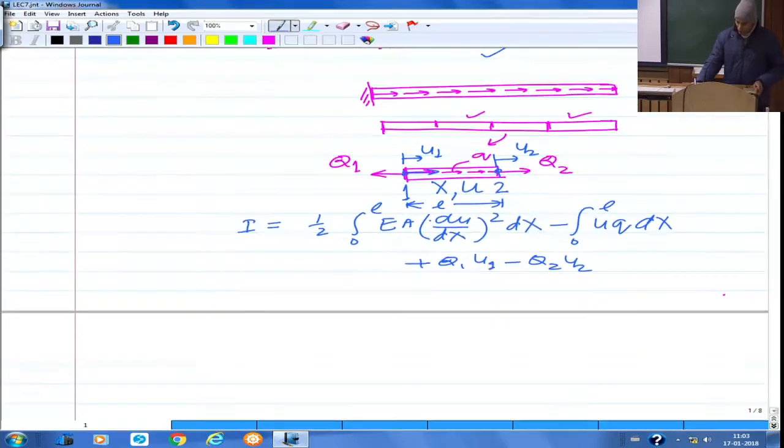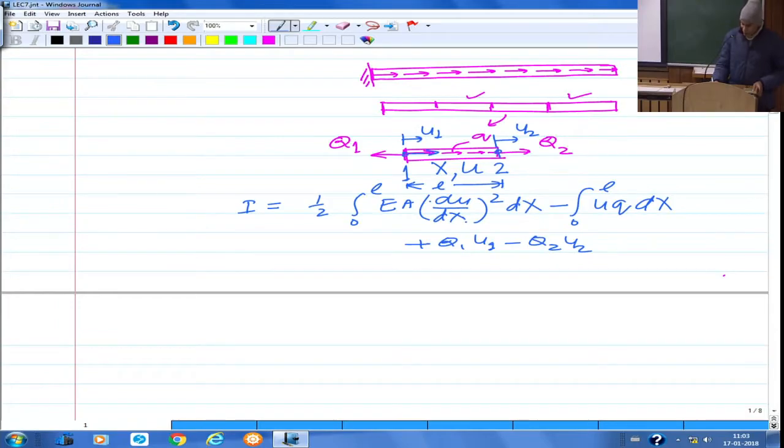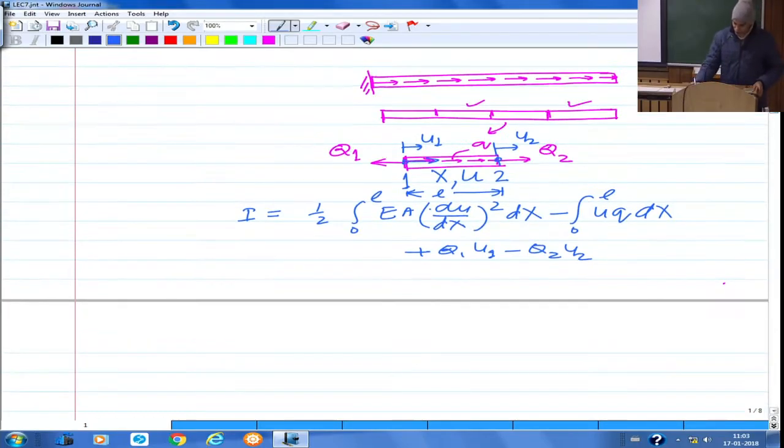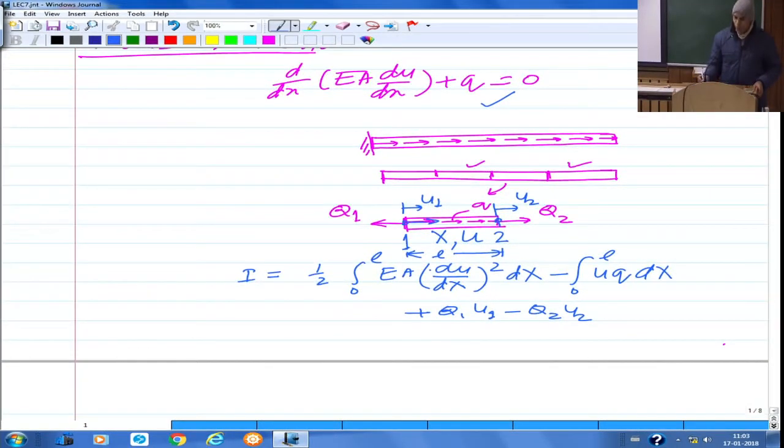Now see what we see here. We had already done the weak form. So for this problem, primary variable is u. So u needs to be the degrees of freedom at the nodes. That is what we said, that u1 is an unknown variable here, that is the value of u at this node. Similarly u2, the value of variable u at this node. These should be degrees of freedom at the nodes, and subsequently we are going to enforce the continuity of this u across elements.